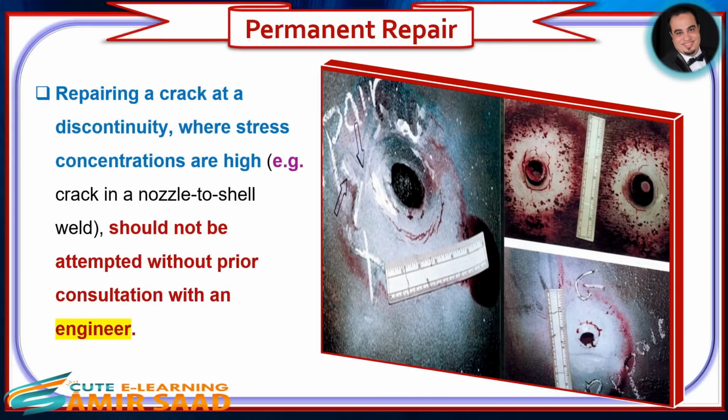Repairing a crack at a discontinuity. Where stress concentrations are high, for example a crack in a nozzle to shell weld, repair should not be attempted without prior consultation with an engineer.